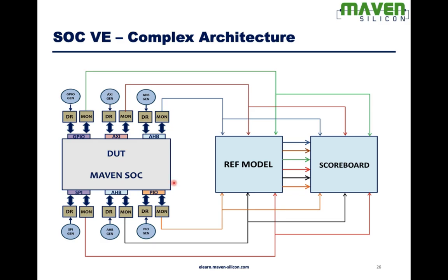Visualize the complexity of the Testbench architecture. Not only the top level connections, within Testbench, look at this. You have to connect driver with the interface, monitor with the interface. We call all these components bus function models. All the drivers and monitors. For every interface, there will be a driver and monitor. There could be multiple monitors also. So you will have hundreds of drivers and monitors in the Testbench, and you cannot make pin by pin connections. That's where you really need the interface concept.